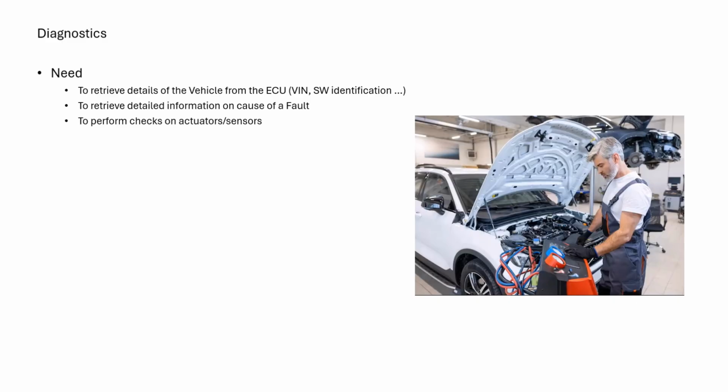So manually we can't go and check each one. A specific set of functions will be there, and with the help of that, we'll run the actuator and sensor test, so that we can continuously check all the actuators and sensors. For that, diagnostics is needed, and also to update the software or other configuration.